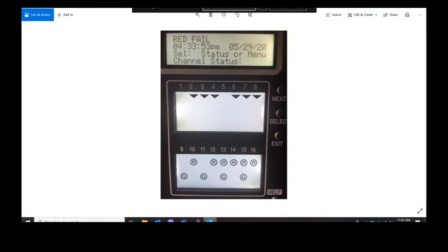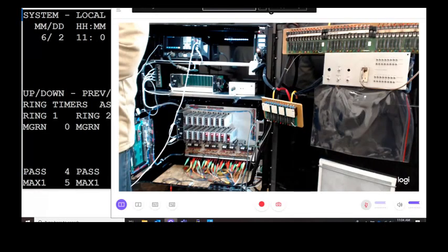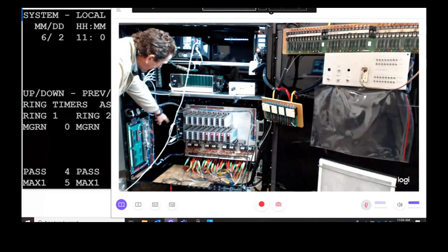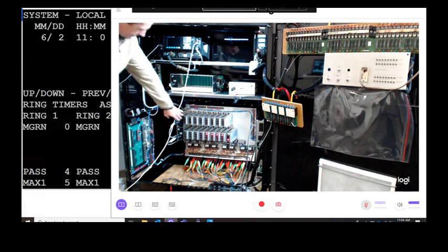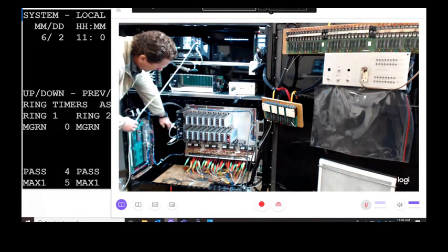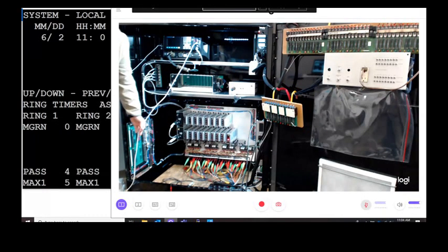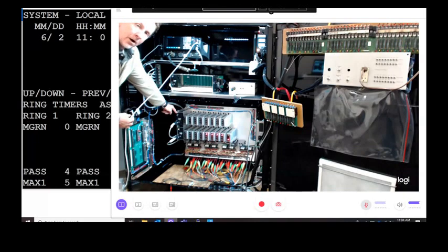So now, let's go back to my controller. Actually, I'm going to take this, and if you can see right here, you can kind of see above my cable. You'll see the lower one right here. You can see the transmit lights, TX and RX, and then there's a green power light. You can just barely see it. But you'll notice I got the same BIU up here. It's totally dark. Obviously, I'm unplugged so it has no power, but if it was plugged in and it was dead, this is what it would look like.